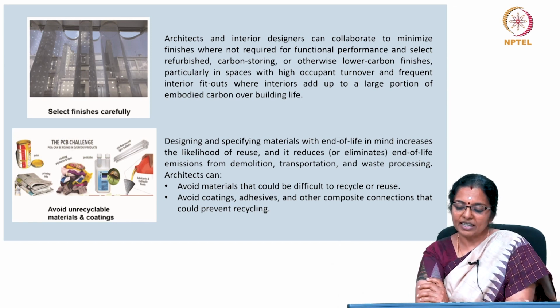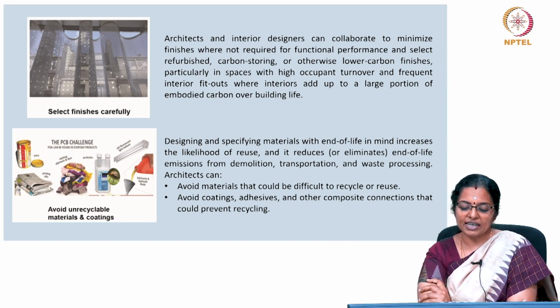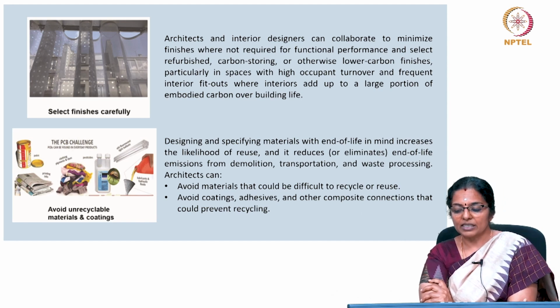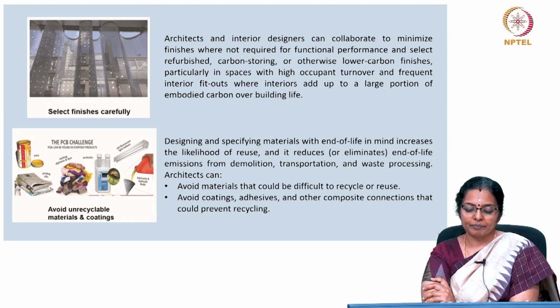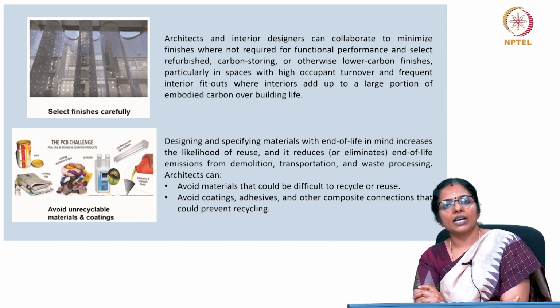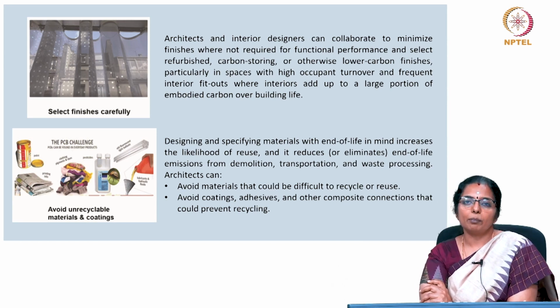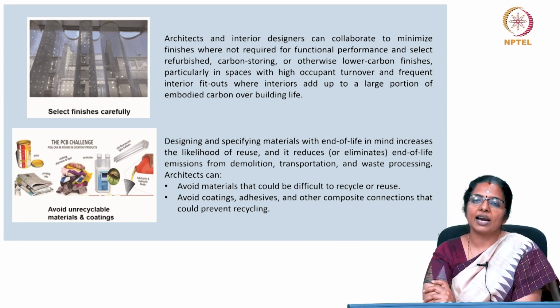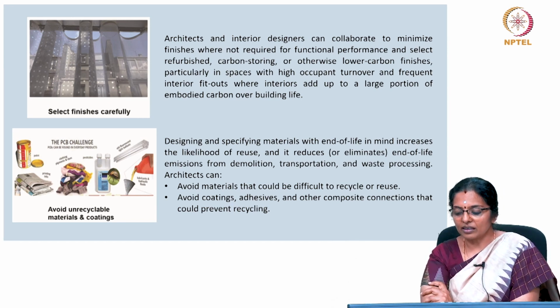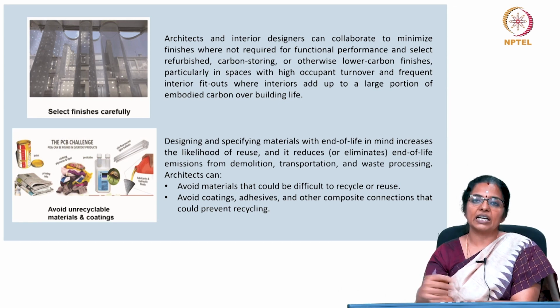Designing and specifying materials with end of life in mind increases the likelihood of reuse and it reduces or eliminates end of life emissions from demolition, transportation and waste processing. Architects can avoid materials that could be difficult to recycle or reuse. This will happen if initially the architect has designed the building keeping in mind its disassembly and adaptability. Avoid coatings, adhesives and other composite connections that could prevent recycling.